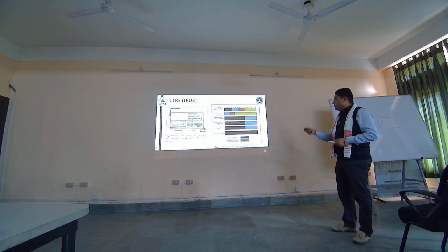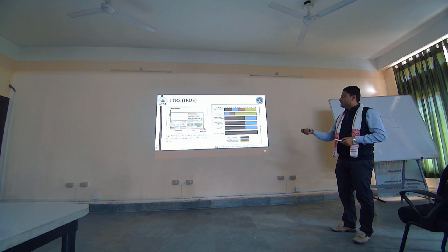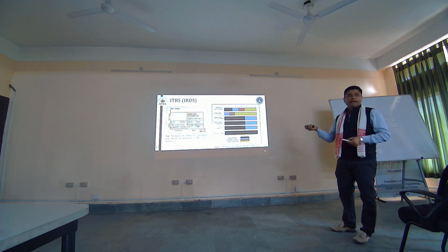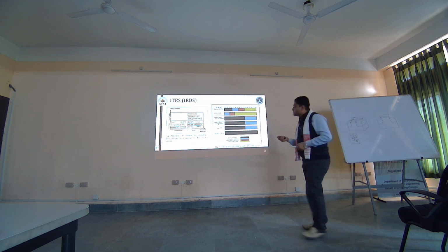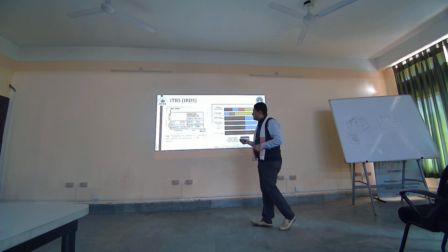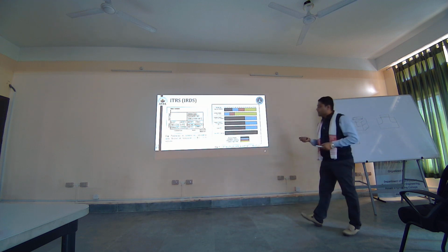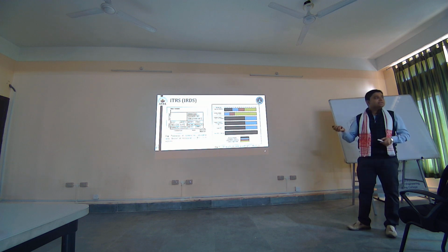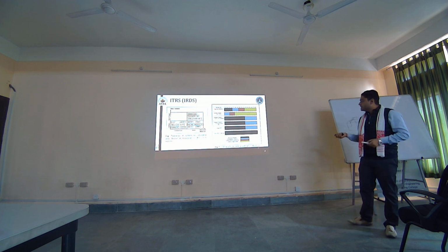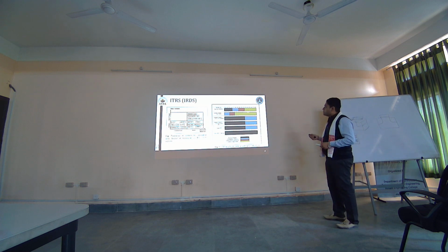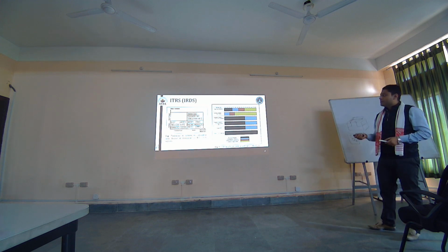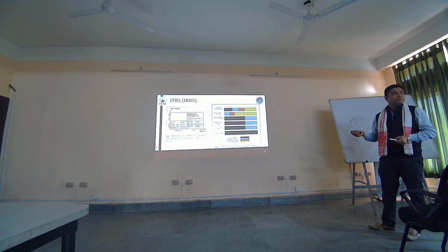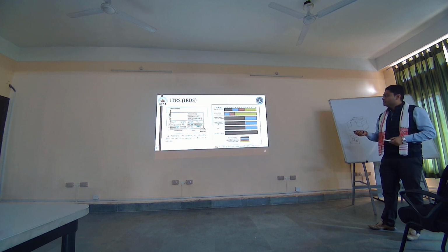Okay, so they published this in 2018, and after that they did not publish this kind of diagram. So in 2018 they gave this scenario where you have these devices: silicon FET, nanowire FET, TFET, then N-germanium, III-V, graphene FET, carbon nanotube FET. So these are some devices which they mentioned. And alongside that, in 2013, they also gave a prediction map for years up to 2028, like which primary devices are going to stay in research and which are going to go into fabrication. So out of that, this tunnel FET is what we are going to discuss now.